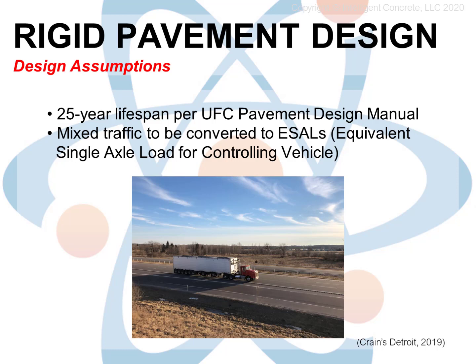The bean counters who developed this method of boiling all traffic down to a single number have determined that a certain passenger vehicle at a certain weight and a certain speed has the same effect on a pavement as, say, 10% or 1% of the controlling vehicle. In other words, 10 or 100 passenger vehicles counts the same as one 18-wheeler. This is just a hypothetical example. The software has already built into it the various conversion factors. We don't have to do that. I've had to do that, and it's pretty much an all-day ordeal. Getting a robot to do the heavy lifting is much better.